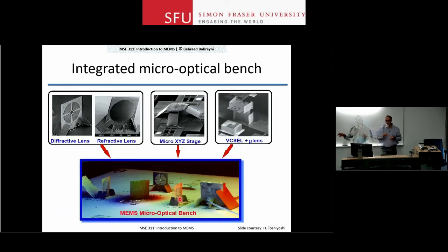So in the early days of MEMS, the miniaturization it offered was very exciting to these optical systems engineers. Tons of interesting devices came about. They were not really too hard to make. You needed to make lenses and movements. But the challenge was that now you have this Fresnel lens. This is called a diffractive lens or a Fresnel lens. It's made on the surface of the wafer, and it's useless to me if I want to do some signal processing with it. I have to make it stand up like that, so the light can go near the surface of the wafer through it. And I can make mirrors, but the mirrors are flat on the surface. I need to raise them, and then I need to lock them in place. So you have all these hinges and locking mechanisms and all that.